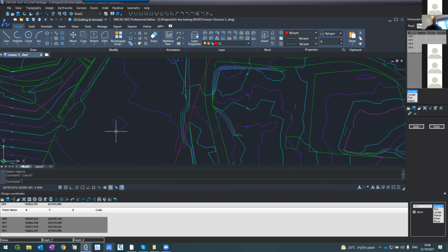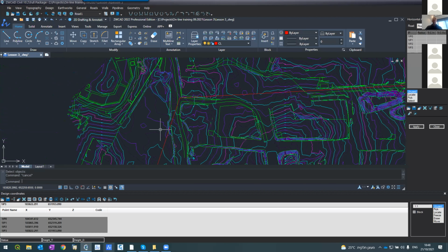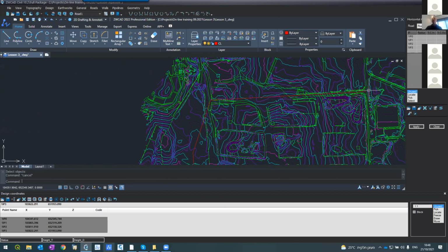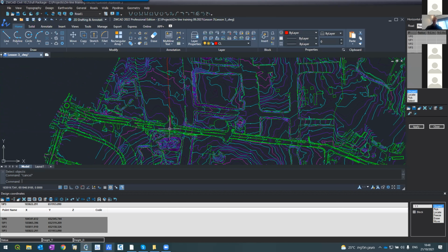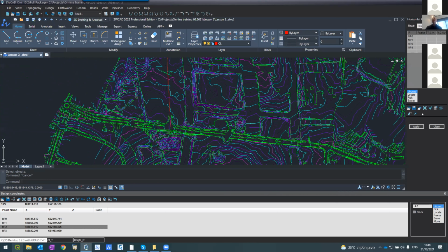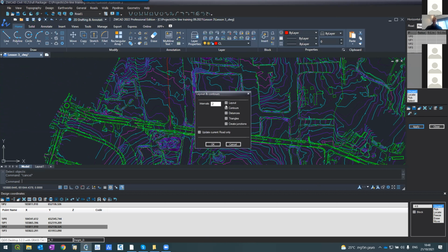See what happened. The system takes this polyline and converts it into roads by defining its intersection points, the IP points. One here, 0, one here, 1, one here, 2, and one here, 3. And the coordinates are here in the database. If I press apply and tell the software to show me the layout, the software will present the new road that we just defined.